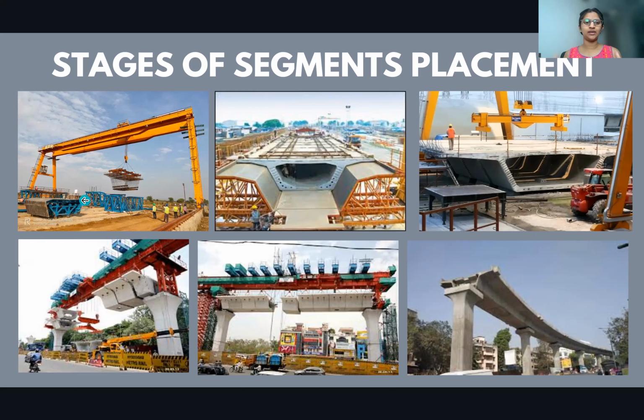Once the whole setup of the reinforcement along with the scaffolding has been placed, the concreting work starts. In order to avoid air voids or air bubbles, and for proper settlement of the concrete, just like how it was mentioned in the pier segment, vibrators are used so that the concrete is completely compacted. Okay, so now you can see this is the whole casing of the scaffolding work of the segments.